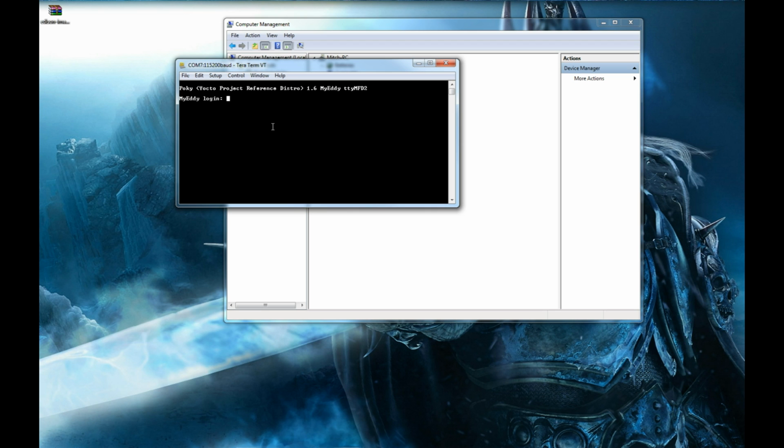Since the Wi-Fi is on and the Bluetooth is on, it basically draws all kinds of power. I said in the previous section about setting my power supply to 5 volts, but you really need to set it higher than that, because I forgot that it draws at least 500 milliamps from the USB port, or at least from power supplies. With that low voltage of only 5 volts on the regulator, it's going to split the power between the USB port and the power supply, and it just doesn't pull enough power. The USB port can only source 250 milliamps on a standard USB port, which is what I have it plugged into. If you have a powered USB port, that's completely different. But if it's not, then you need to up the power, which I did.